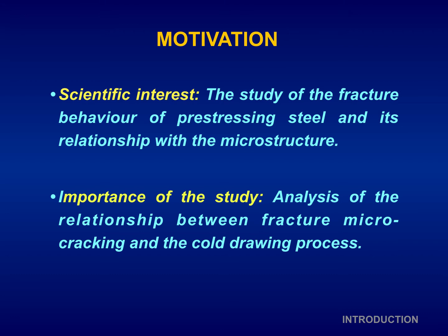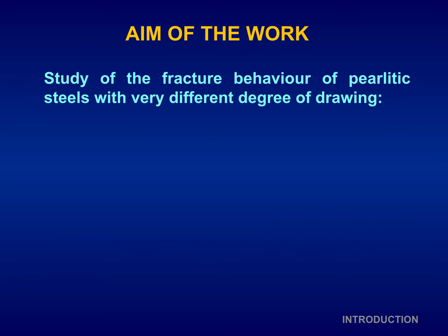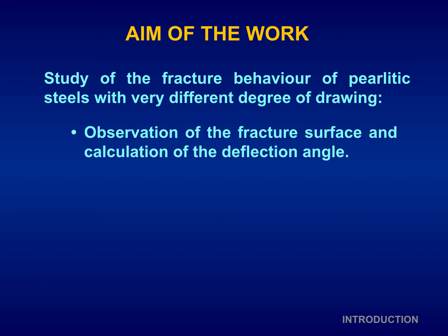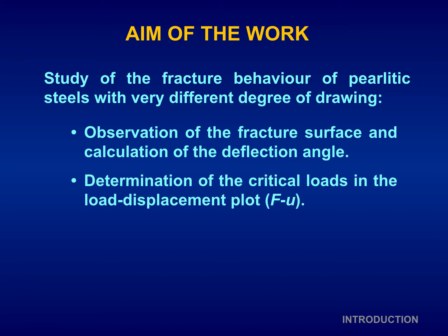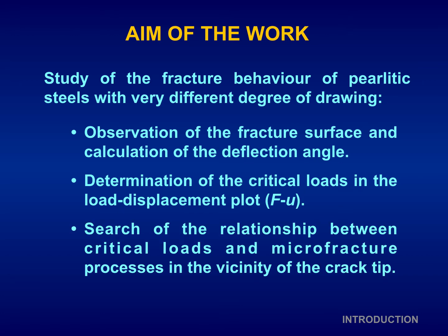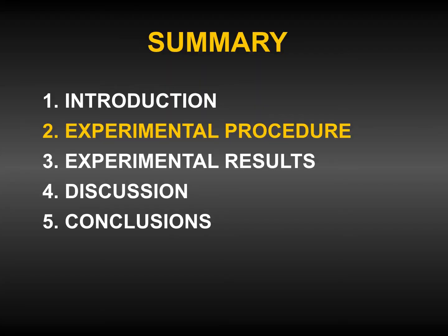The importance of the study is the analysis of the relationship between fracture microcracking and the cold drawing process. The aim of the work is a study of the fracture behavior of pearlitic steels with very different degrees of drawing, with observation of the fracture surface and calculation of the deflection angle of the crack path, determination of the critical loads in the load displacement plot, F-U, and a search for the relationship between critical loads and microfracture processes in the vicinity of the crack tip. Second, experimental procedure.